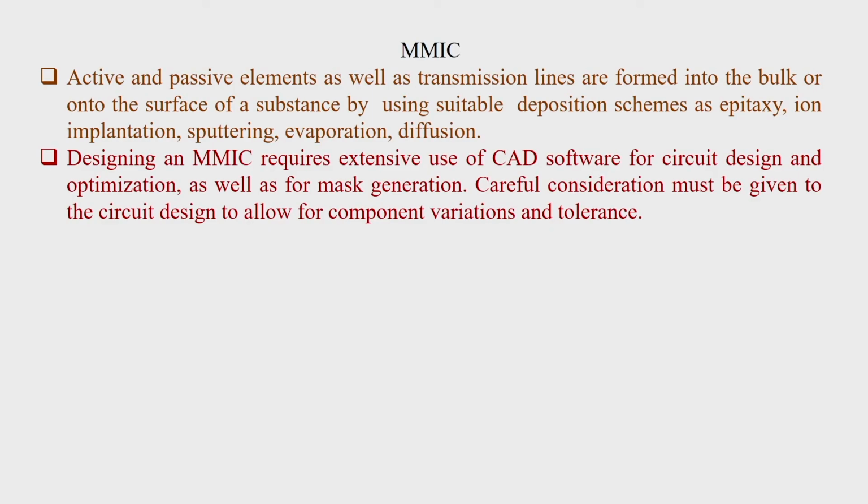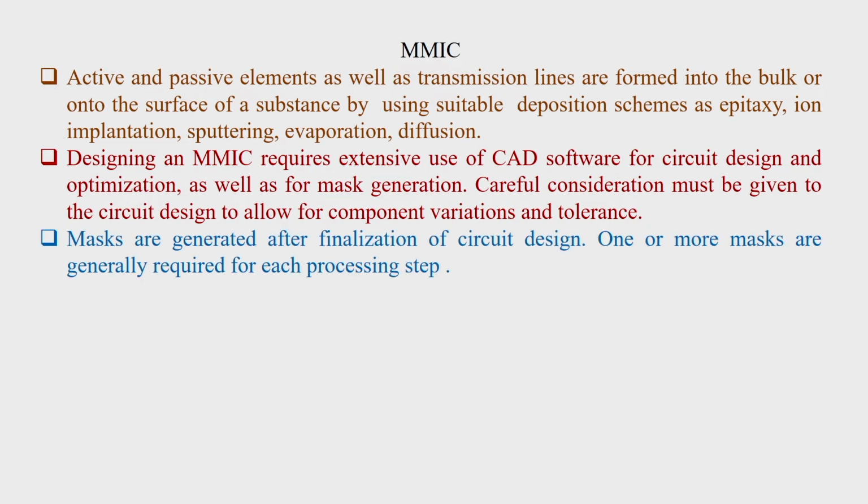Careful consideration must be given to circuit design to allow component variations and tolerance. Masks are generated after finalization of circuit design. One or more masks are generally required for each processing step.